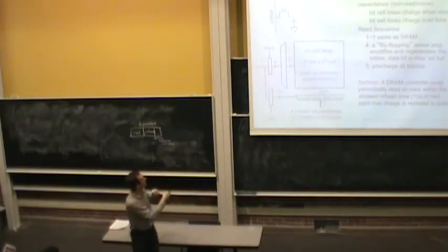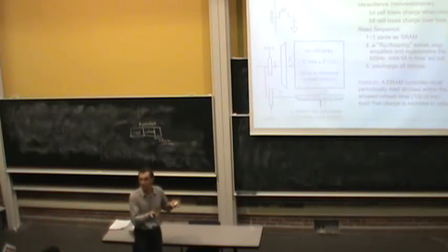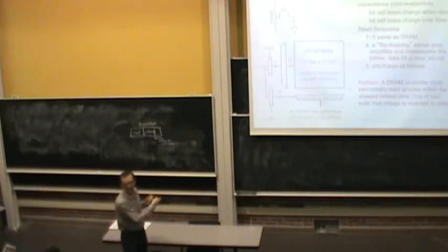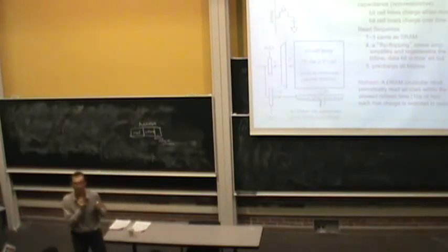You first supply the row address, 16 pins, through the 16 pins, and then that gets latched in DRAM. And while that row address is being decoded, in the next DRAM cycle, you only supply the column address. And that's the only reason. That's why you would do this, whereas on chip, SRAM, you don't have that pin constraint.